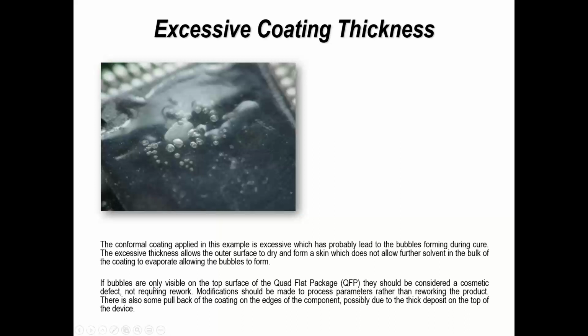Now, we mentioned bubbles or voids in the surface of coatings, and this is a good bad example, if you like. And really, if you saw bubbles in the surface of the coating like this on the top of this package, it's a QFP package, then again, it's not going to have any impact whatsoever on the functionality or electronic performance of this particular product. However, they don't meet the requirement of the IPC standards because there are bubbles there.